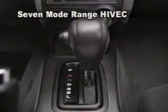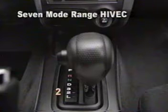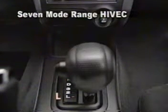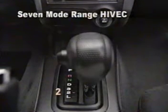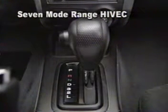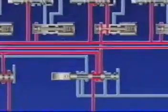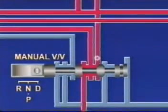In the Hivec automatic transaxle, in which sports mode is not adopted, there are another 3 driving ranges, except D range, regardless of 4-speed or 5-speed. Since the position of manual valve remains the same in all forward driving ranges, the oil pressure flow from manual valve to underdrive clutch remains constant regardless of speed.